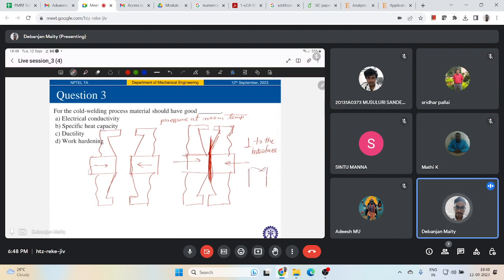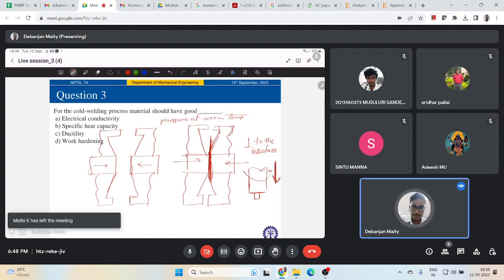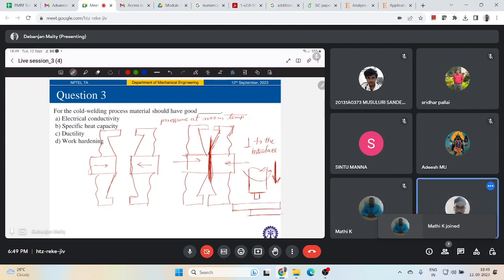So this was your tool, right? Let's say this is my tool, and it has a pin. You rotate the tool and apply the plunge in the downward direction. This is my interface, which is normal to this downward plunge direction, right? But you can always feel some reaction force in the lateral direction. So this is a vector. It's not that you will get force in the z direction only. The reaction forces are there in x and y also.